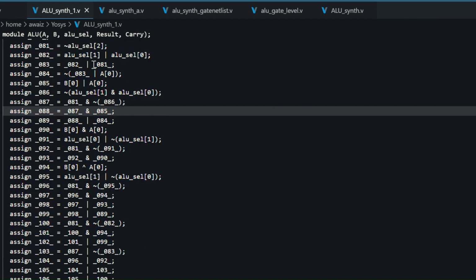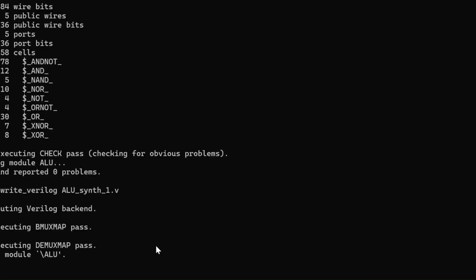After selecting the ALU, we will be doing technology mapping. In this, we will be mapping a Liberty file, which is a standard cell library, so that we can get a hardware-based design. We will be doing more synthesis, with technology mapping, so we can have cell delay, area and power information that makes it easy to understand.